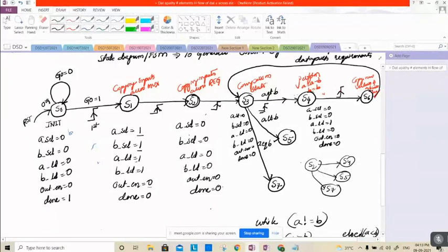But the problem is simple. What work should happen in S2? Loading, copying inputs to the register. This should happen, right? It is one particular thing. Now if the comparator is also functioning, and the comparator inputs are coming, outputs must be generated here. So these two operations must take place in a single clock cycle. Right?